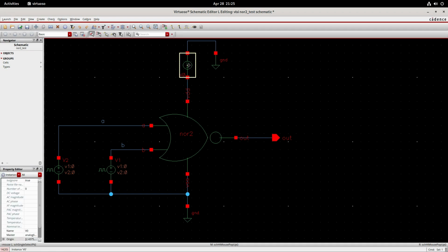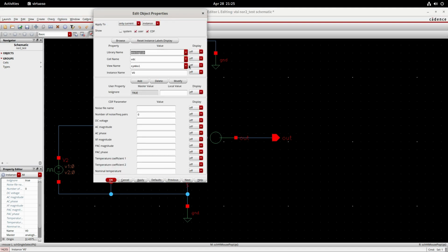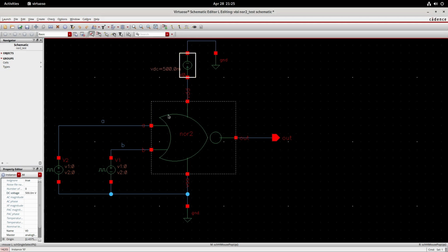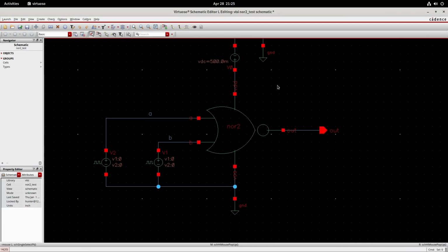Now we need to give the parameters. Press this DC voltage supply, press Q. Q will get you into the properties. The DC voltage, here I'm using 0.5 volt DC. You can use 1 volt, 1.3, 3.35 or something, whatever you need.